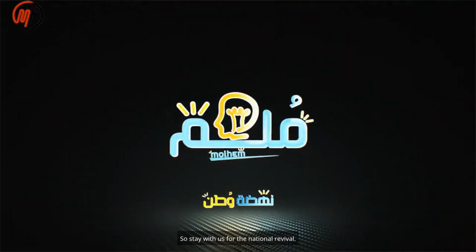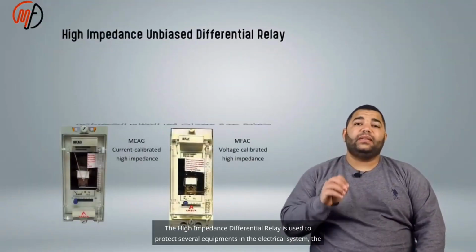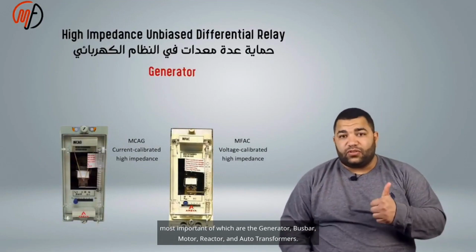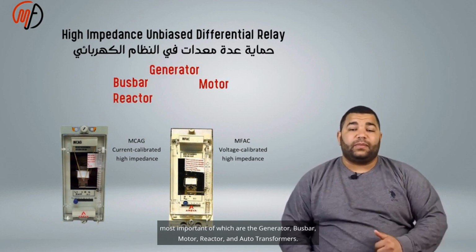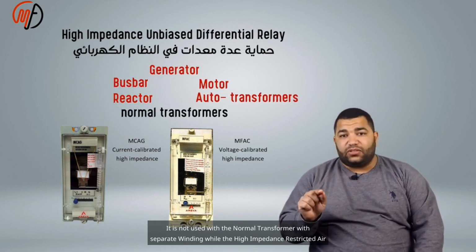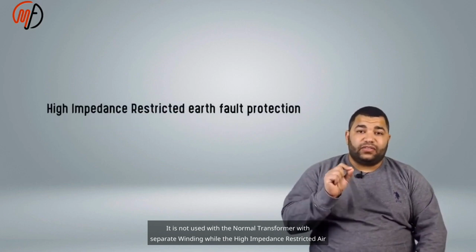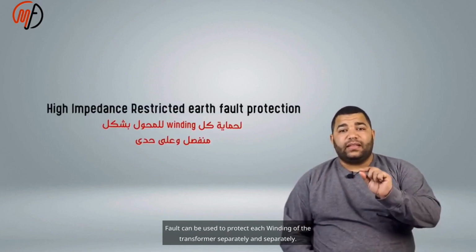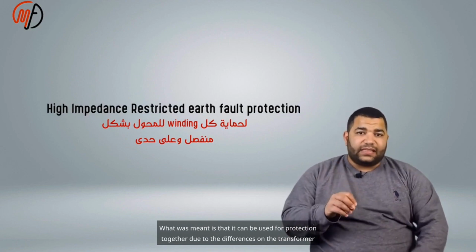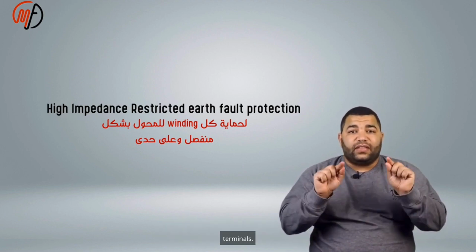The high impedance differential relay is used to protect several equipments in the electrical system, the most important of which are the generator, bus bar, motor, reactor, and auto transformers. It is not used with the normal transformer with separate windings. The high impedance restricted earth fault relay can be used to protect each winding of the transformer separately.